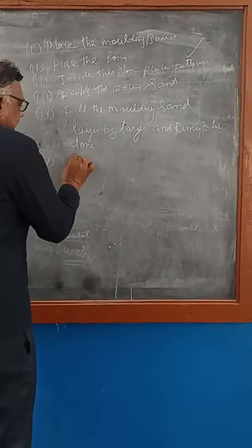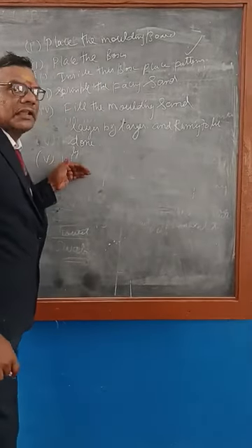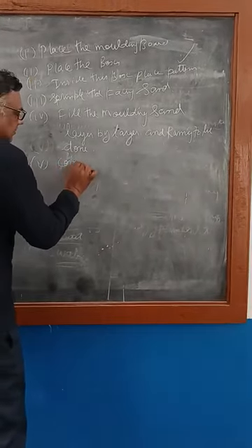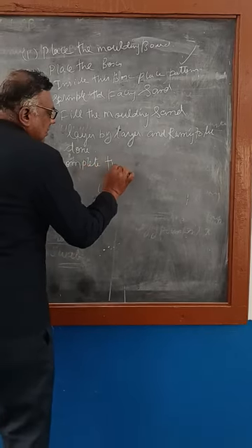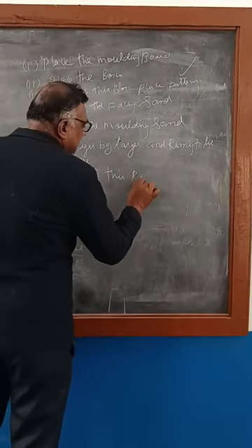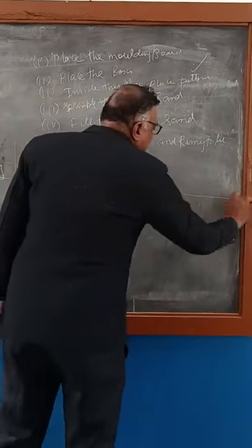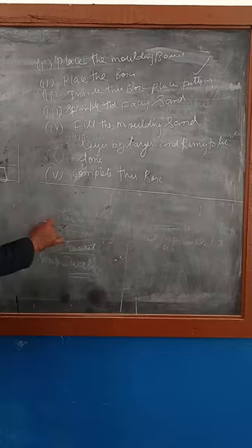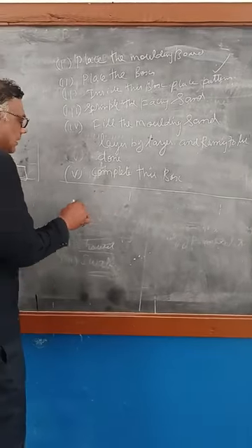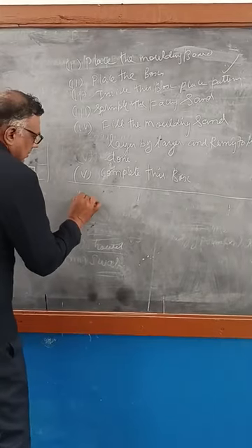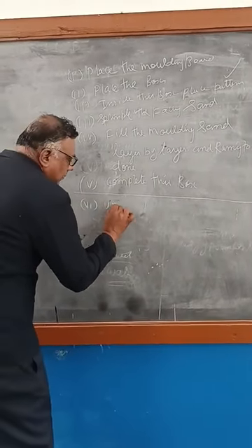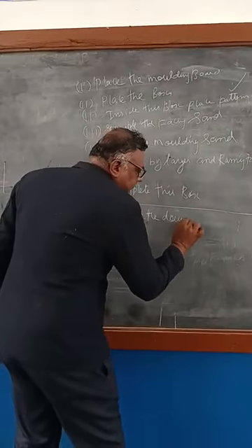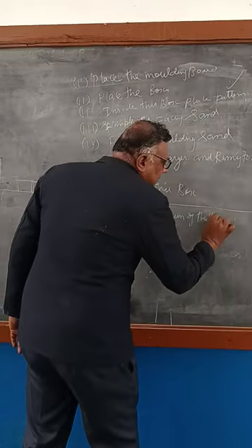Similarly, form the other layer and keep ramming until this box is complete. So the first box is over. After completing the first box, you have to make sure the molding board stays in the same place. Next we have to tilt, or turn upside down, the filled box.